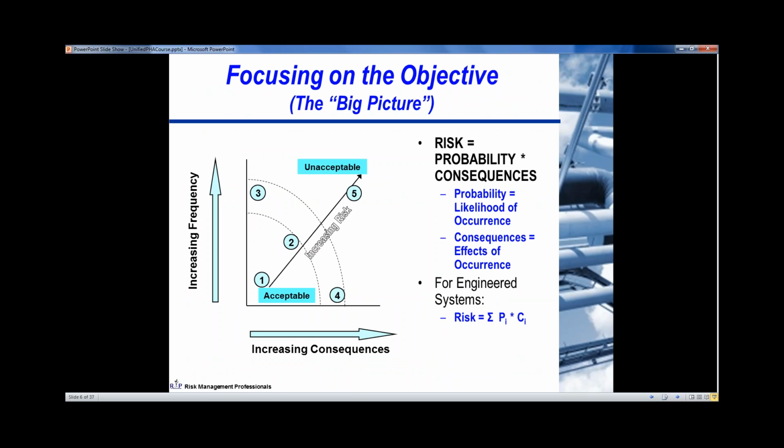What are these tools? Most of these tools are scenario-based, understanding what can go wrong. In this image, you see 5 different scenarios where you're looking at likelihood and the severity, and you're trying to link those together to determine the importance of the scenario. That's a fundamental aspect of understanding the hazard, whether there are any gaps in the design, and what you do about it. Obviously, if you're using the HAZOP and LOPA tools, the quality of that work is very important for clearly identifying the scenarios and where you want to go with things.